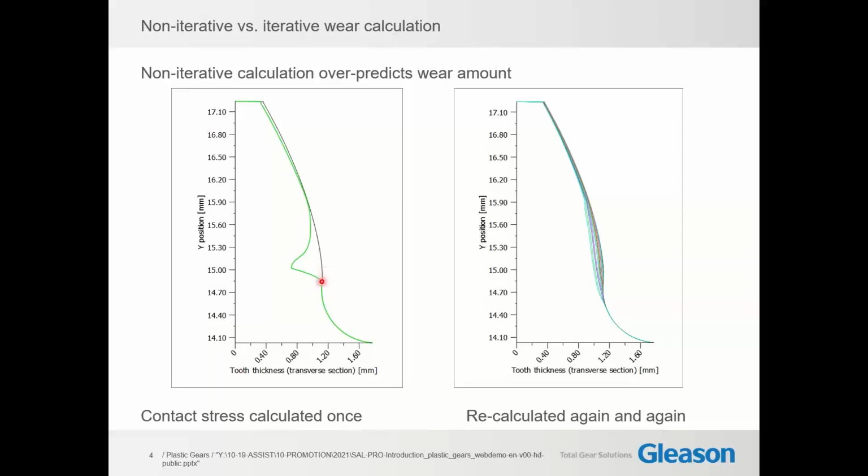At the start of mesh, which is then in the dedendum area of the driver, we have a high contact force at the start of mesh when the pinion engages with the tip area of the gear. So we have a high contact pressure, and of course at the start of mesh we have a high sliding speed in the direction of the tooth form. Since then both parameters, contact pressure and speed, are high, the resulting wear is highest down here.